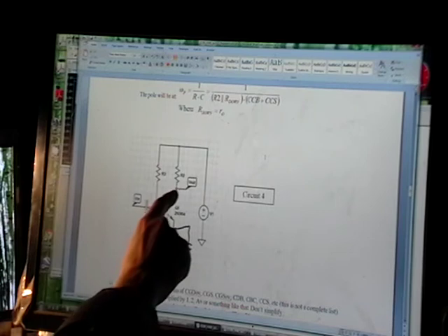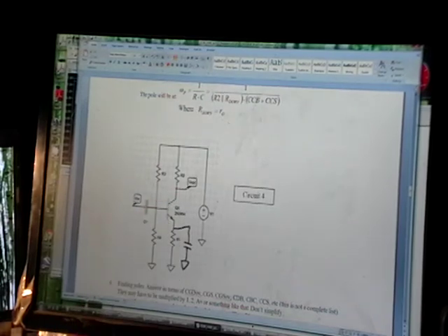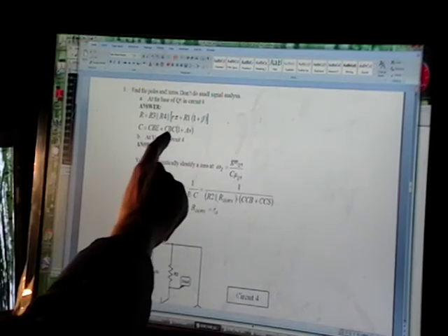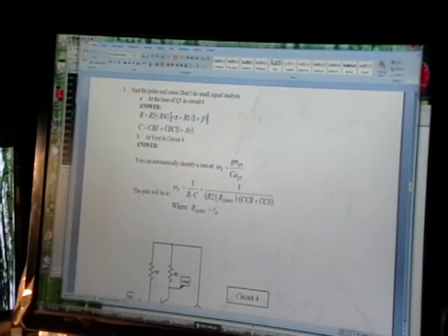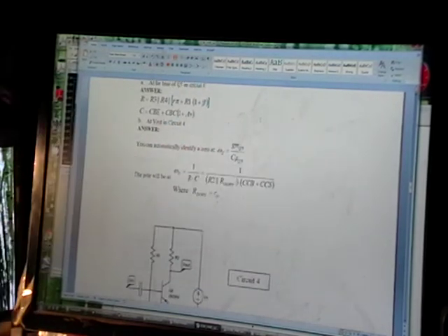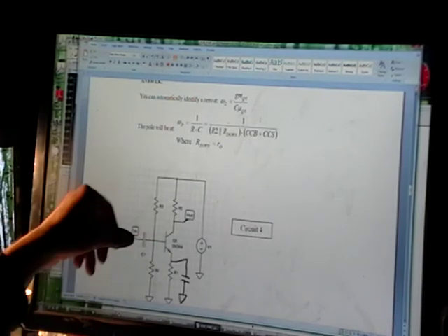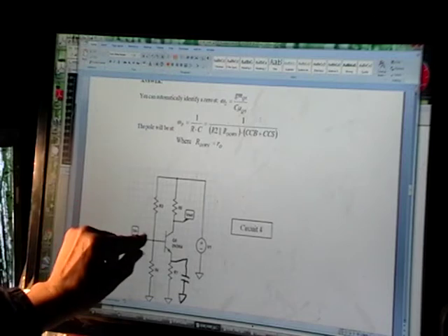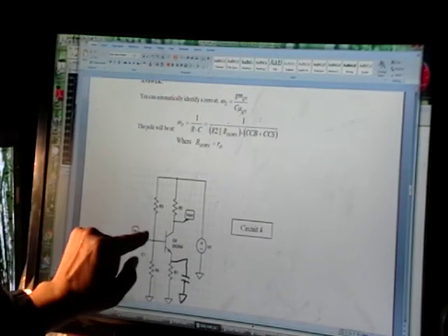And CBC, yes, you've got the Miller effect, so you have to multiply it by 1 plus AV. Okay, to find the pole, it's 1 over RC, so we just found the C. To find the R, and again, I'll get rid of this capacitor, you look in all directions, front, back, up, down, and see your resistances. And right here you have R3.